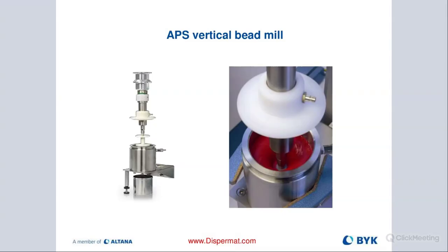Once the milling cycle is completed, just open up the drain plug on the bottom, and then you hook up an air hose into the socket in the cover that's embedded right there, and that basically allows you to pressurize the top vessel and then force your milled material into the container below.